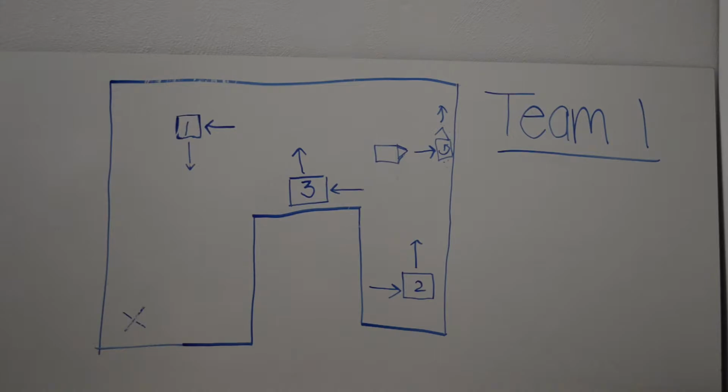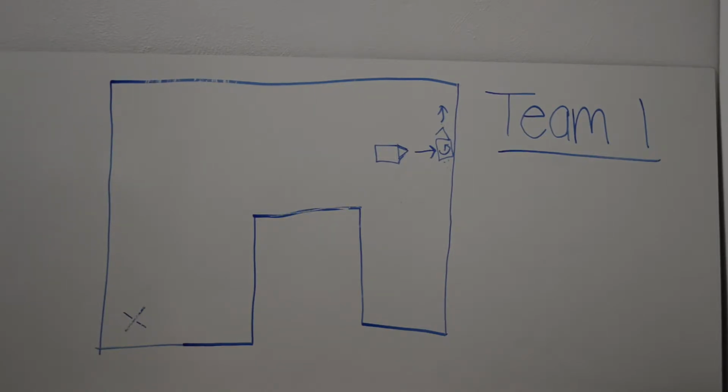Due to time constraints, some parts of the project were dropped from our design. Ramps were entirely dropped from the project, as well as location determination based upon distances traveled. Location determination was, however, still performed with the previous history of turns, which proved to be sufficient for many kinds of ramps. Additionally, while starting from random locations on the map worked for the simulated rover, the real rover had to start next to a wall. Finally, while the real rover was quite effective at making left turns, the real rover did not always perform right turns when needed. This caused the position determination algorithm to not work effectively on the real rover.